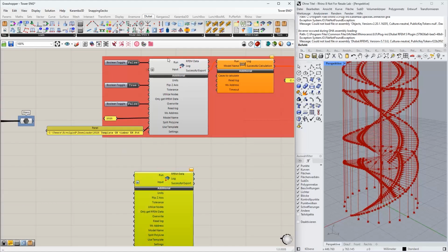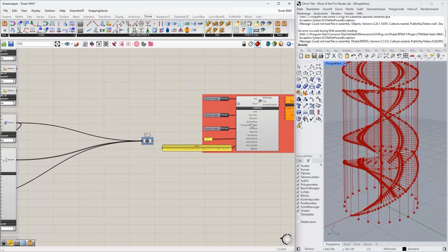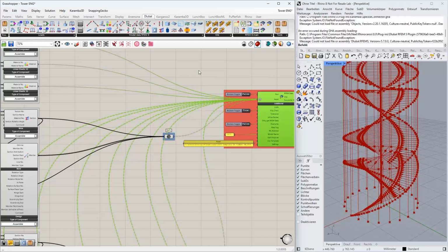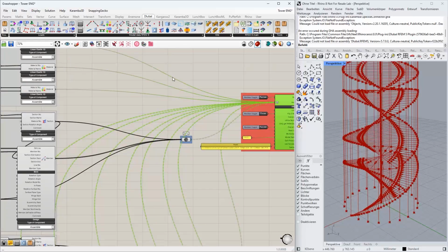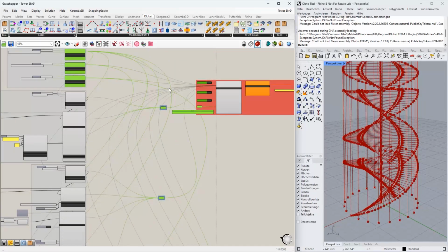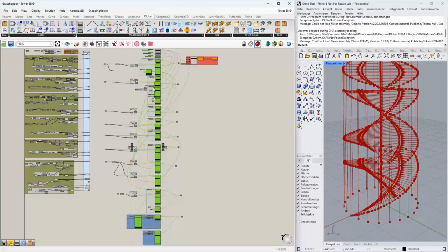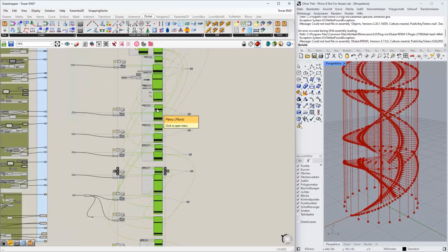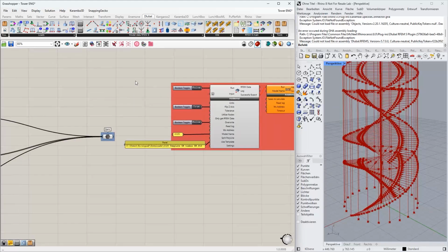Here the export component. First, you can define here a Boolean toggle to run the export. If you activate it, the export is running. For the input, you connect all the Dlubal components we use. It's easy to check if you click the component, press Control and left arrow button, you see which components are connected. Now it's directly connected to materials, and if I look, okay, every RFEM component is green, they're all connected to our component.